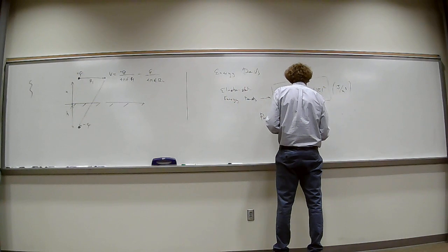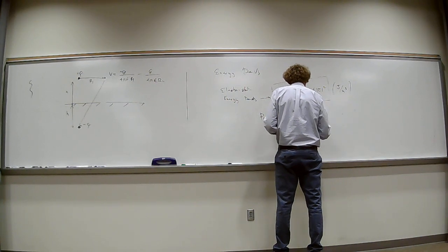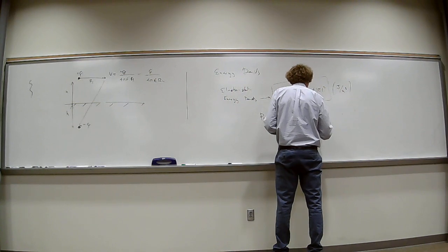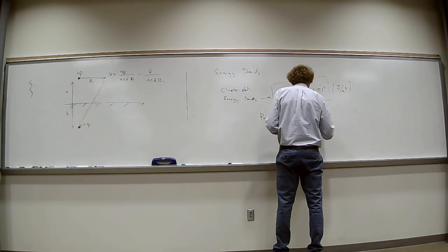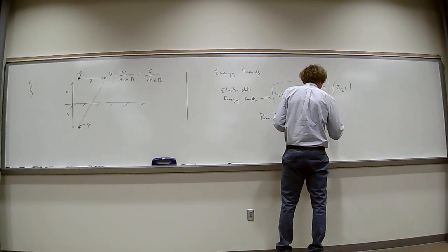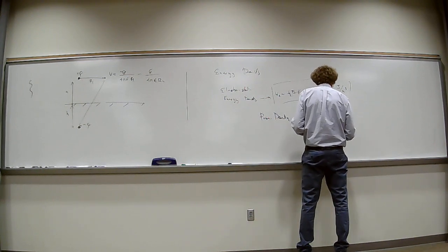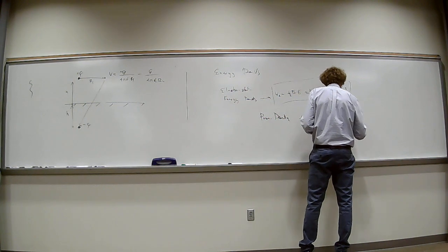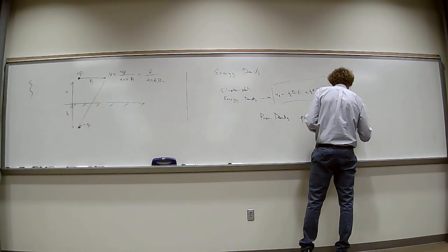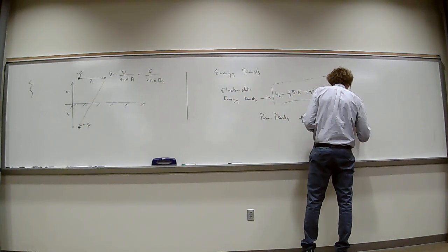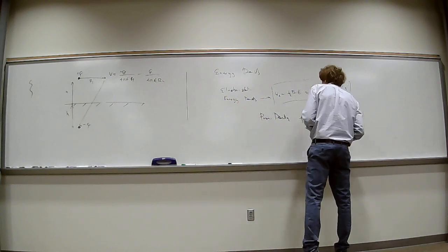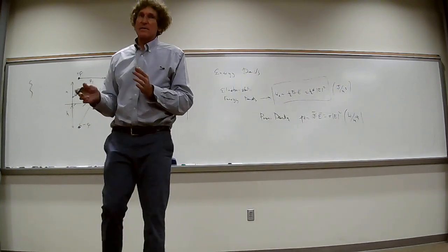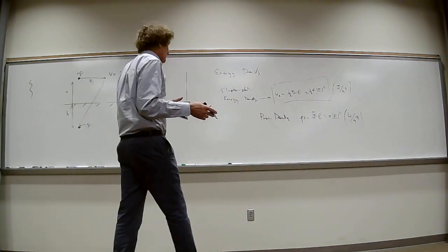Power density, I'm going to use the symbol PD, is going to be sigma times, it's really J dot E, but J is sigma E, so the way it's usually rendered is sigma times the magnitude of E squared, and that's watts per meter cubed. I'm just doing this for a reason, to make sure I contrast things that you can confuse.